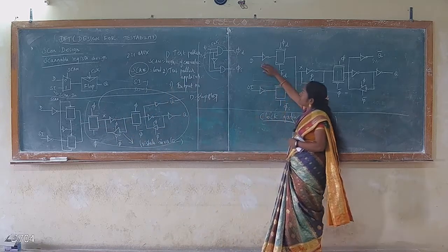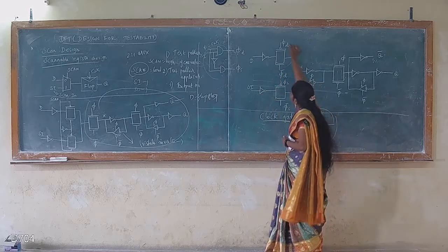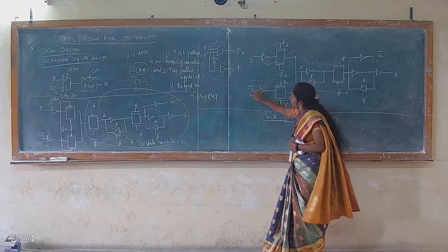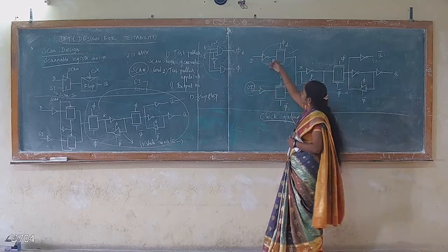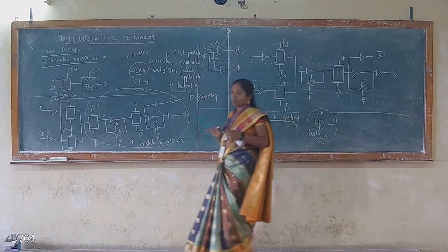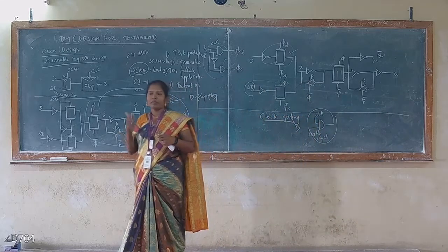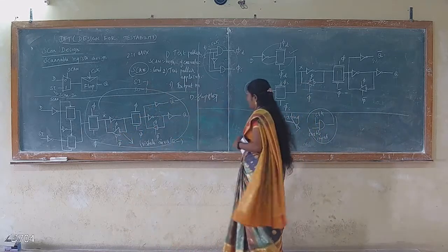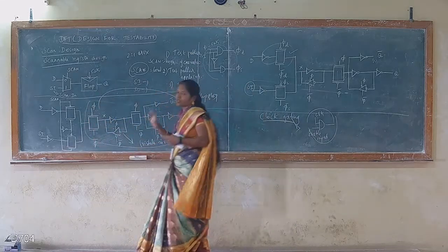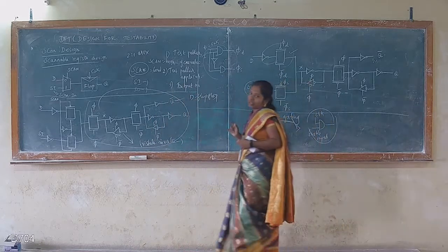Now we have separated the D flip-flop and the scan in input, and if scan in is not used, we can stop the clock for the circuit. So using clock gating, we are stopping the clock for unused portions of the chip. That means we are expecting the same setup time as in the ordinary flip-flop. So this is the concept of scan design, serial scan, parallel scan, and the scannable register design.